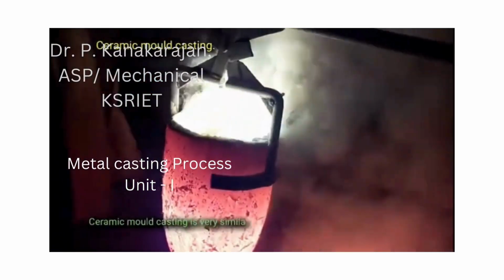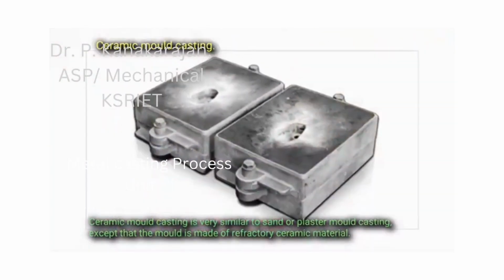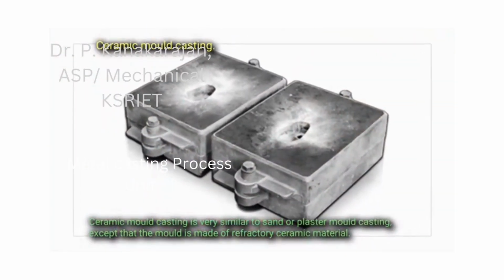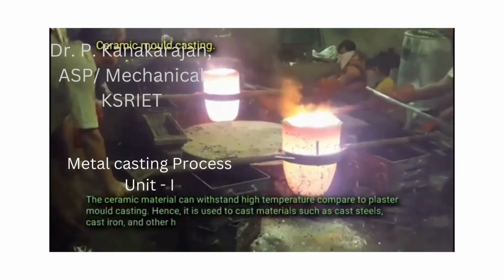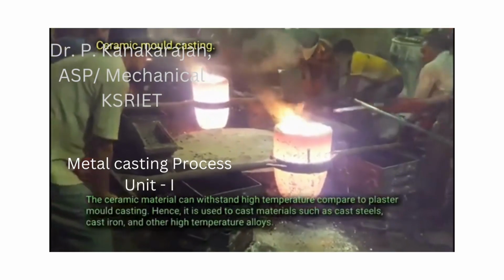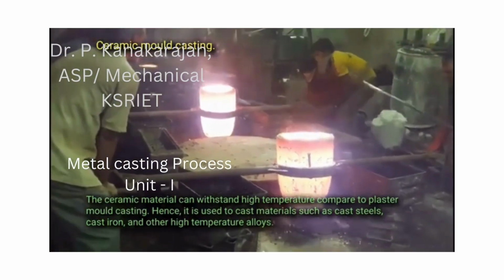Ceramics mold casting. Ceramics mold casting is very similar to sand or plaster mold casting, except that the mold is made of refractory ceramic material. The ceramic material can withstand high temperature compared to plaster mold. Hence, it is used to cast materials such as cast steels, cast iron and other high-temperature alloys.